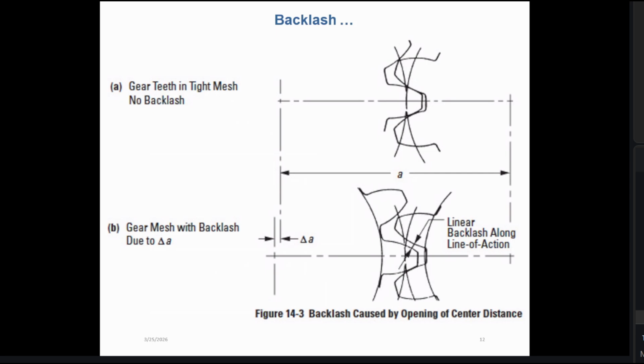So if you can predict the operating conditions, and if you can put a clearance that may be reduced with the operating temperature due to the expansion, that will be better. But to maintain the reliability and the continuous operation, to avoid any disruptions, we basically put a small clearance. We call it a backlash.